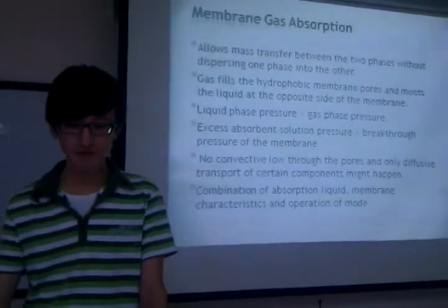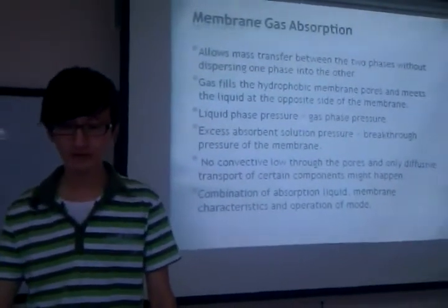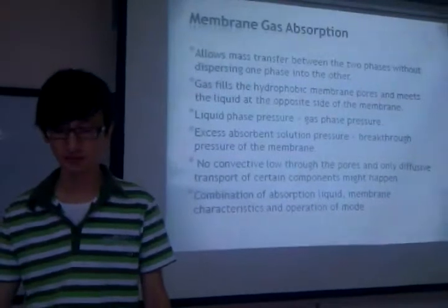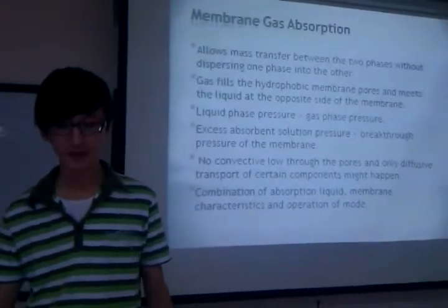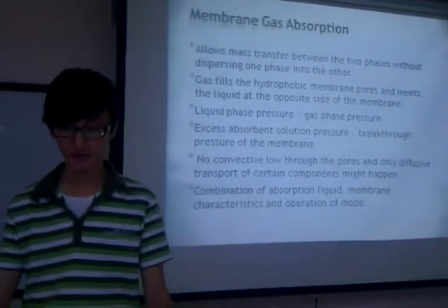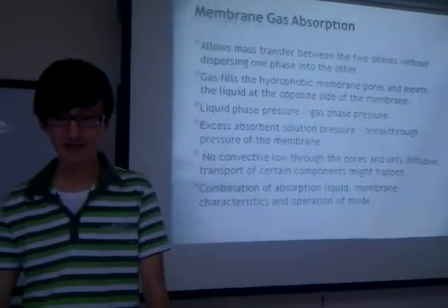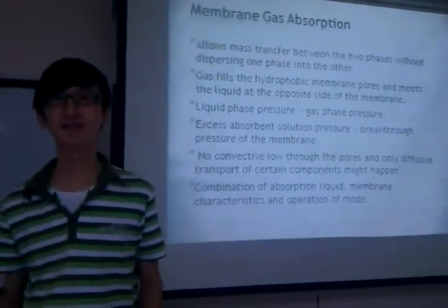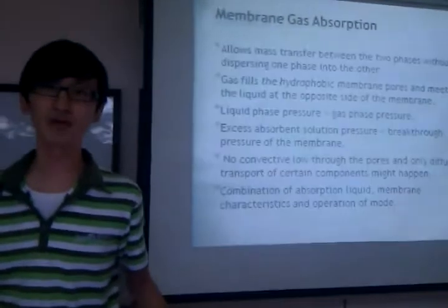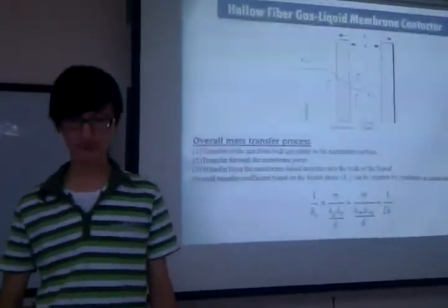There is no convective flow through the pore and only diffusion transport of certain components might happen. The combination of absorption liquid, membrane characteristics, and mode of operation determines the selective removal of the membrane.